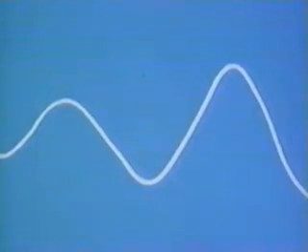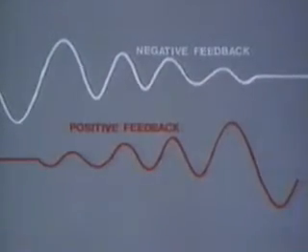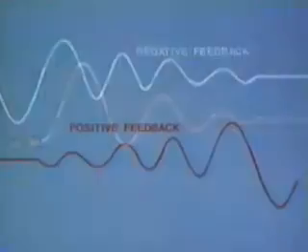She is experiencing what engineers will recognize as insufficient phase margin, with the phase lagging more and more with each turning of the steering wheel. Her delay in turning the wheel resulted in excessive phase shift and positive feedback. Although, as we can see, positive should not be construed as synonymous with desirable. This is a diagrammatical example of negative feedback. The error diminishes until it disappears altogether. So, a negative feedback situation is good. A positive feedback situation is bad.